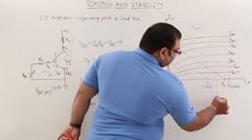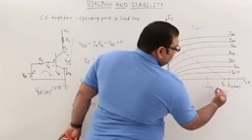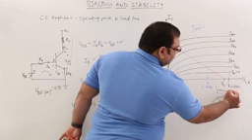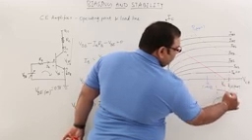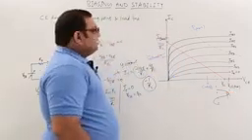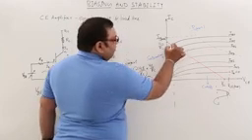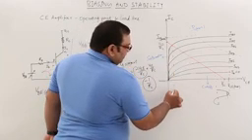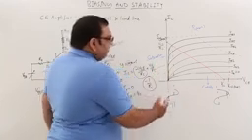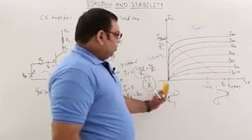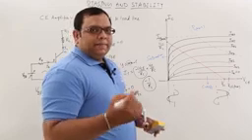When you are operating the transistor at this point, if you take the output swing, whenever the swing crosses VCE, it gets distorted. When you take maximum signal, whenever it is crossing, this output portion will be distorted. Similarly, if you take the operating point early here, whenever it is crossing the point where VCE is 0, the negative portion will be distorted. So where you have to consider the operating point?